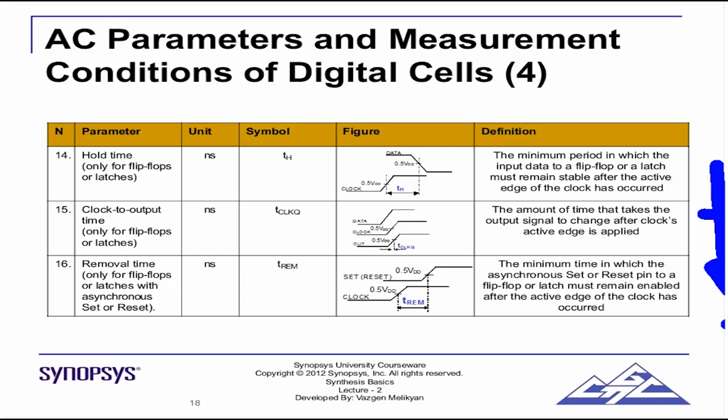So in fact, if you add up TSU and TH, the setup time requirement and the hold time requirement, it tells you that whenever the clock changes for a flip-flop, there is a window before the clock and after the clock. The before window is called the setup time window, the after window is called the hold time window. The data signal should not change in this window. If it changes, the operation of that flip-flop or latch is not guaranteed. Setup time and hold time, you will see a lot of equations using setup time and hold time, but everything starts from this basic definition.